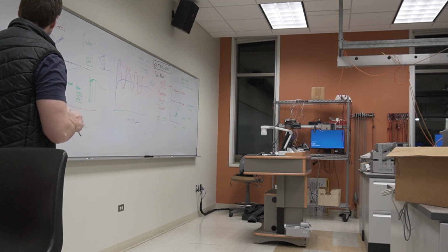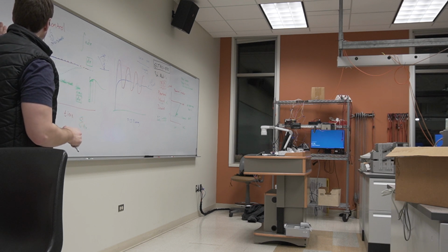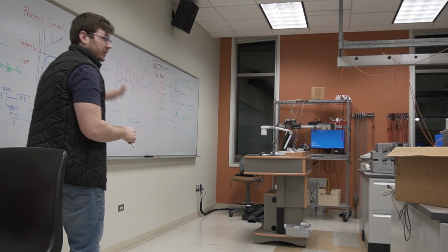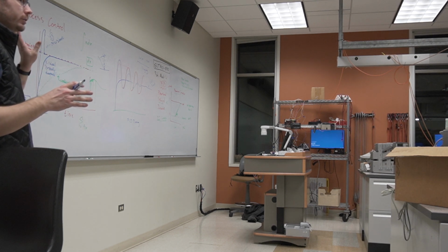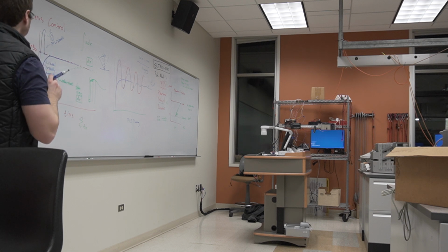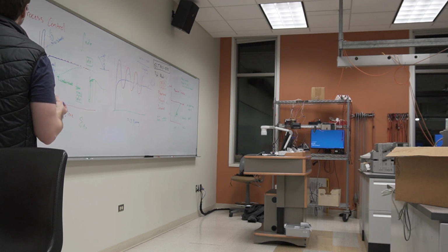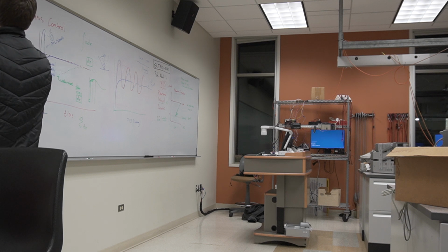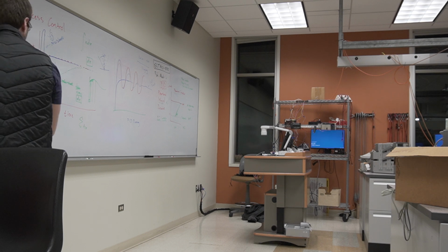So in lots of cases, our output can either be on or off, right? Our heater's on, our heater's off, or we could have a more gradual output where we could control how much current is going into our heater, for example, or control how hard our motor is pushing back against this arm to try to right it. Not necessarily all on or all off. So what this really does more often than not is control the duty cycle. Okay, duty cycle.